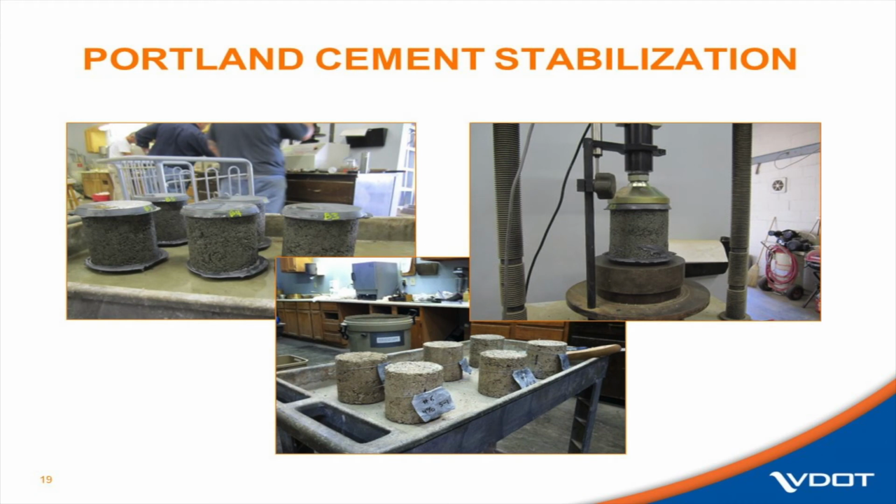These are some photographs of a laboratory that used to work for me. One of the things I wanted to point out in this picture is sample management. You've got a lot of samples. You've got to keep them numbered. Here they've got wire tags, with duct tape for a tag. But once they go to compressive strength testing, you can't have that, so you have to transfer a different number onto them. So laboratory management's important.